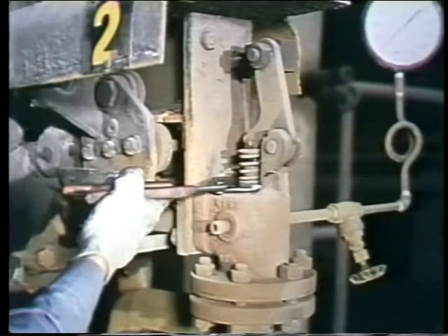The soot blower's valve may be a problem if it's not properly adjusted. Finally, corrosion and erosion can cause the nozzles to become blocked or come loose, and the end of an element may blow off. Well, what do you do if any of these things happen?